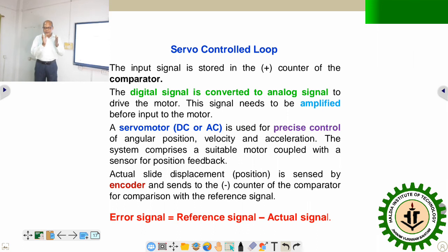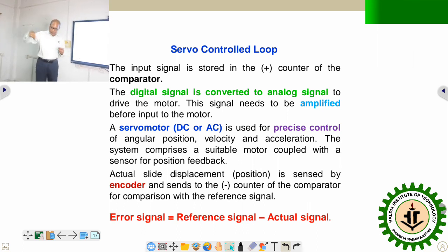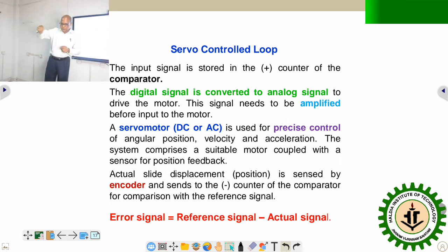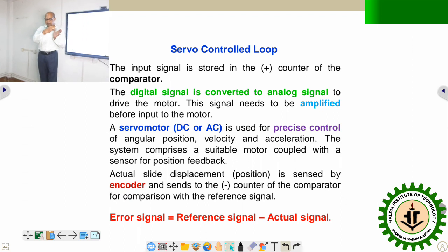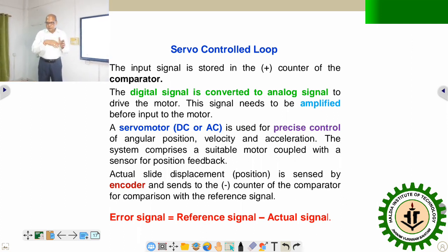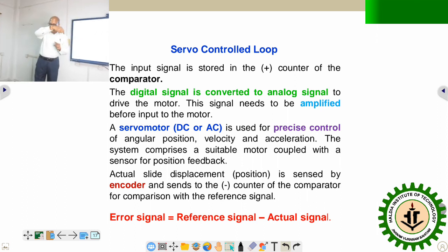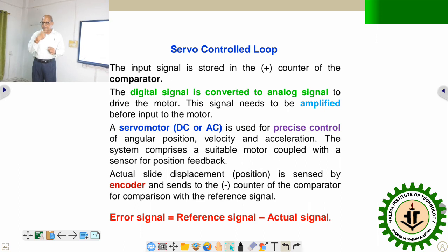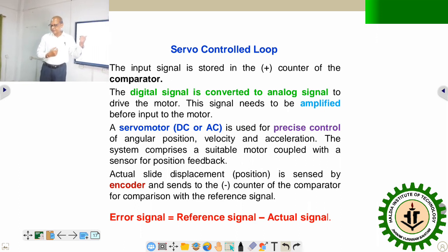So what is in the program? Suppose just for an example, say your movement in a lathe along the z axis while undertaking a turning, suppose G01 Z minus 50 F.2. This is a program value. So this interprets that along the Z minus direction, the tool should supposed to move by 50 millimeter, maintaining the speed of 0.2 millimeter per revolution.